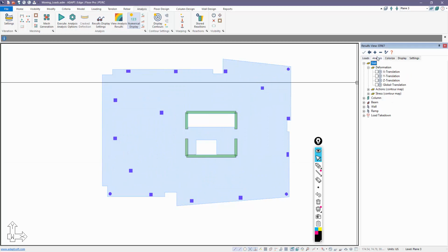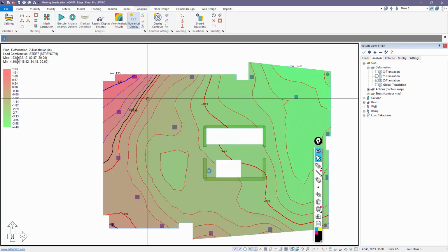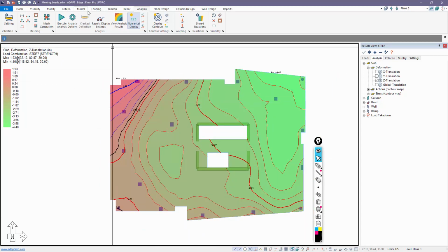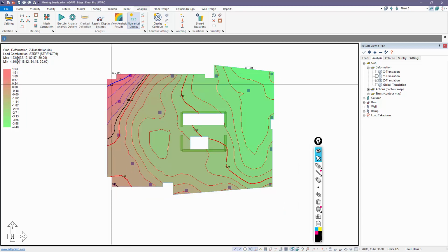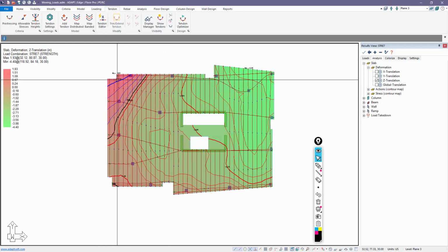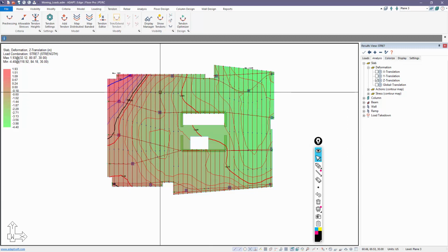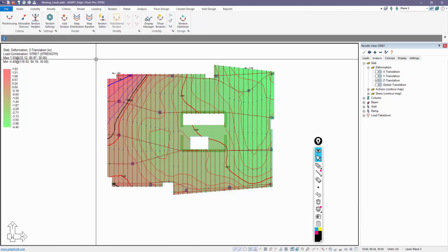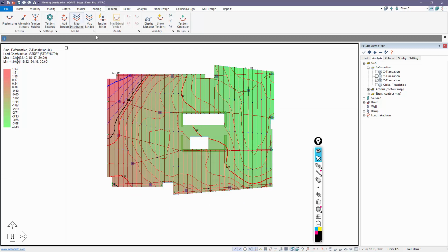If I look at the vertical deflection again, there's still some disconnectivity at this location. The issue is actually being caused by the tendons. This is a set of tendons, and because the strength includes the hyperstatic action for the tendons, that's solved uniquely. So we need to eliminate that from the combinations to actually produce a valid deflection result when we have post-tensioning cables considered.